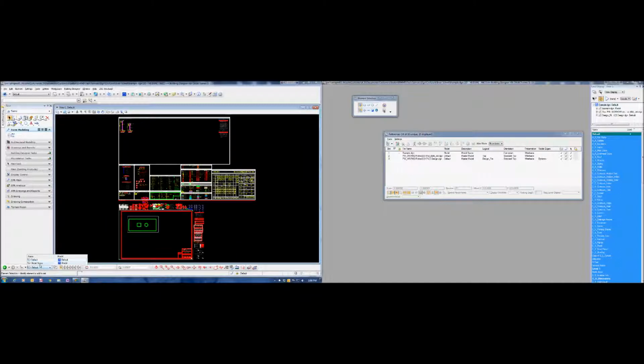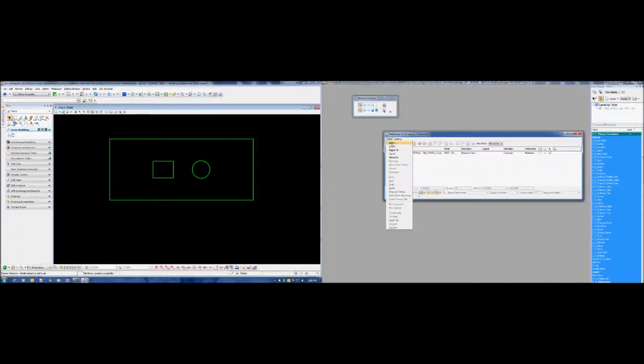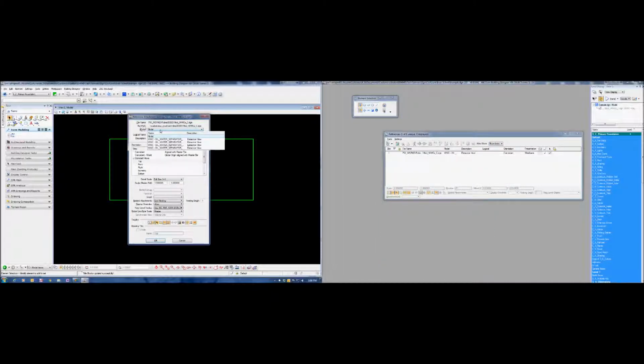Next, we want to come back to model and say we got section cuts that are with this. Well, we are going to go back to civil mod, go back to your same model, make sure it's set to interactive again, say OK, and we want to select a section cut. So this one we want to also say top so it can get placed interactively, 1-to-1, and we don't need nesting on these things. So say OK. So there is a section cut.